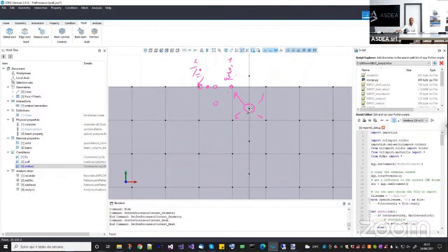And this is very different from the rigid link, because in the rigid link the concept is different. These four nodes are slaves, and this one is the master, so the entire body will move rigidly. While in my case, my mesh can move freely, and the inside node will move as a weighted average of the others. So it will not add any stiffness to the surrounding element.